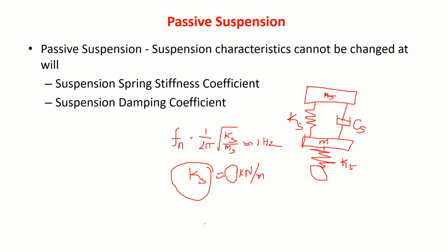But in reality, you see, I must have designed this for a laden condition, that is loaded condition. By chance mass varies, means say unladen condition, or there is less mass, definitely this value will change, frequency will change. So resonance frequency will change.